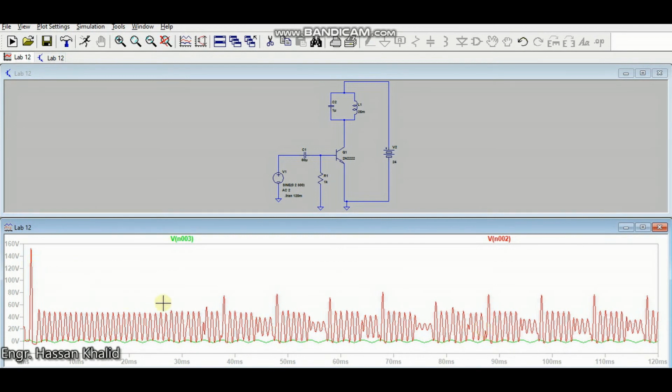Secondly, there are damped oscillations after regular intervals of time, in which the capacitor was being charged, secondly it was charging the inductor, and thirdly the inductor was feeding the energy to the capacitor once again, but the magnitude of that energy was each time lower as compared to the previous state.